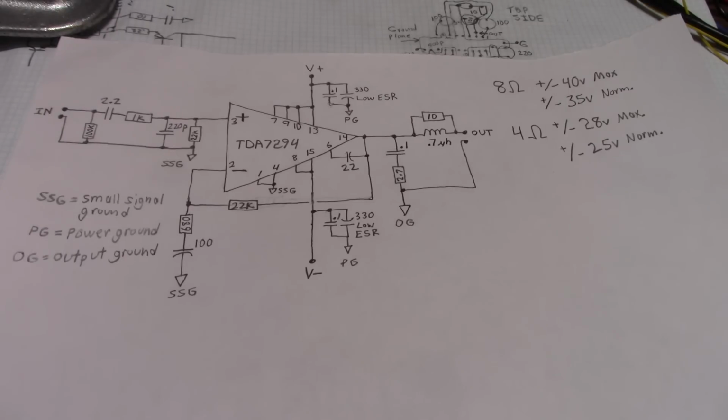Okay, before I wrap this video up, I want to leave you with a schematic showing the recommended circuit for the TDA7294. I'm not really happy with the one in the datasheet. I think they skimp on component values, leave some important stability parts out. Because the bean counter that looks at the datasheet will see smaller components or fewer components, say, oh, this is nice for application, but I don't agree. I think leaving parts out is not a very good idea.